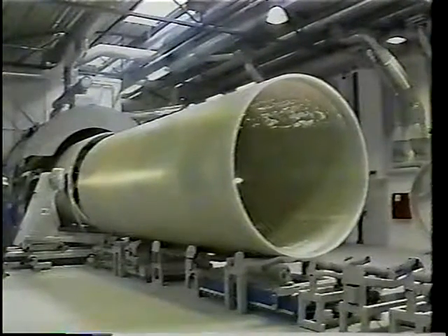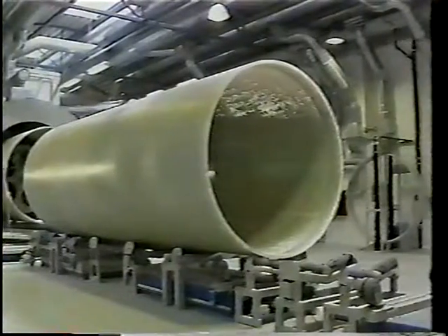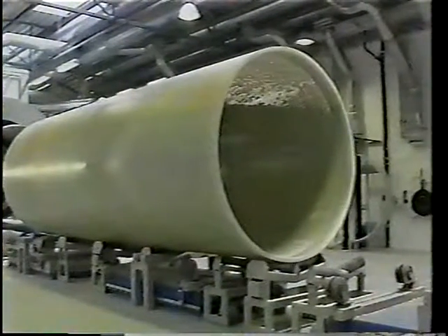Glass fiber reinforced plastic, often called simply GRP or fiberglass pipe, are also used for pressure and non-pressure applications. Some fiberglass pipes are wound over an internal mandrel with continuous fibers, known as filament wound, chopped fibers, or both. This pipe, however, is centrifugally cast in an external mold and then cured.